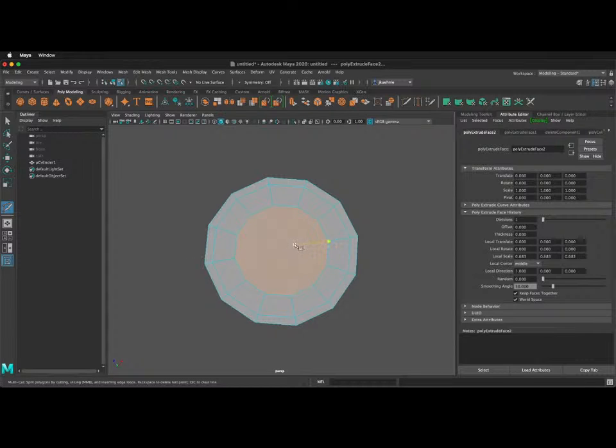We need to make quads out of this. The easiest way to do that is to draw a line in the middle and then connect the perpendicular lines. Sometimes it's hard to select a vertex, so if you click and hold on an edge and drag to that vertex, it'll automatically select it. And then remember to right-click to accept.